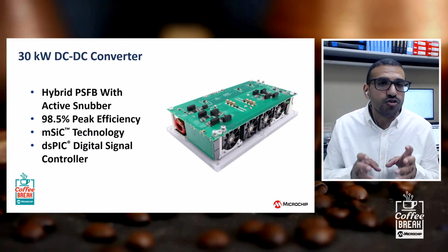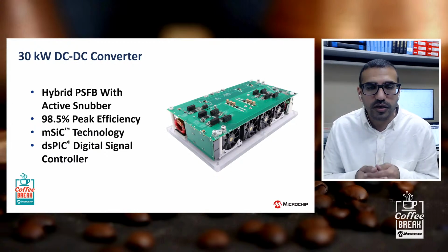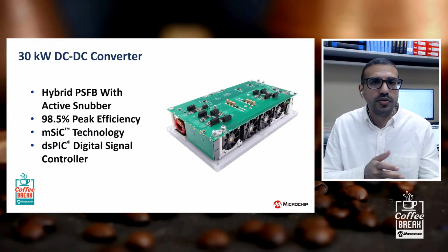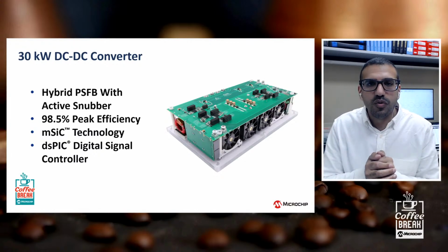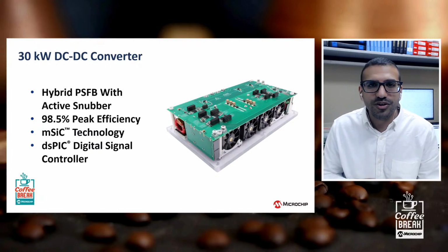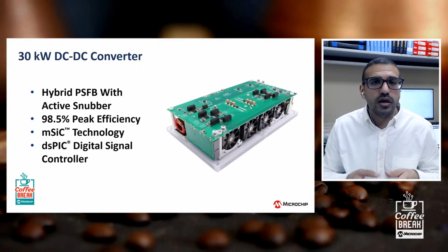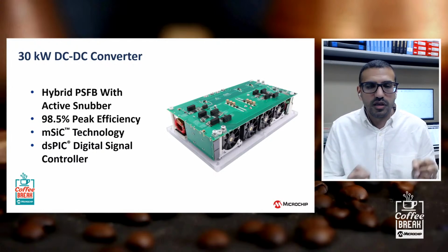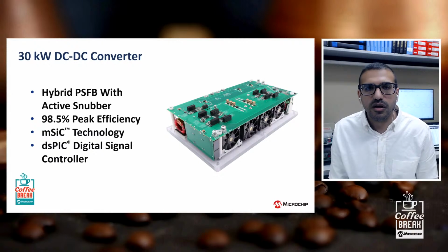In terms of the controller, we have a dsPIC again, and we provide all the control software for both this DC-DC converter and that PFC you had just talked about. We provide all the design files, whether it's the Altium schematic, the layout, the bill of materials, the Gerber files, and the software, so that customers can take these designs, send them out to get built, and then can evaluate it.